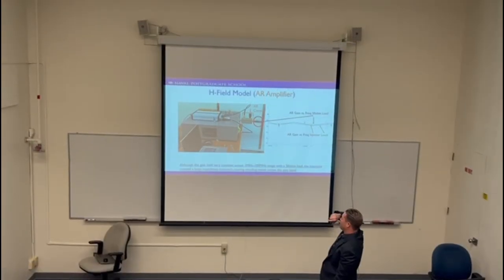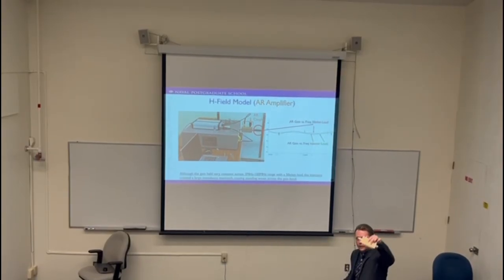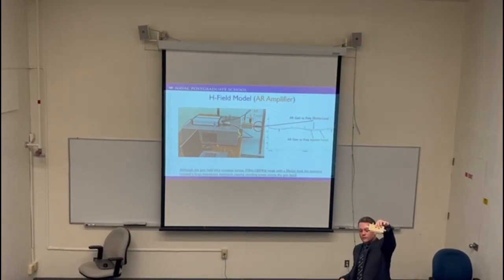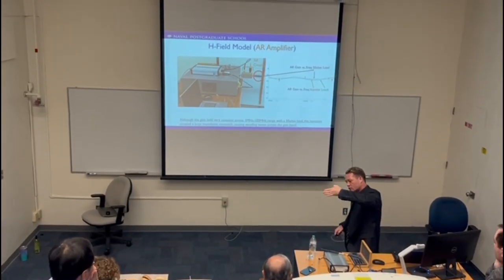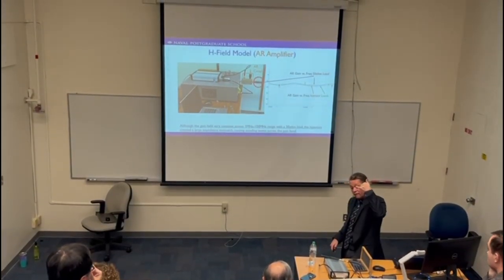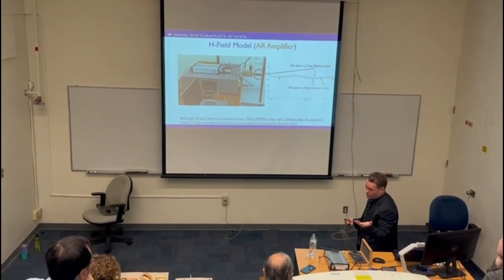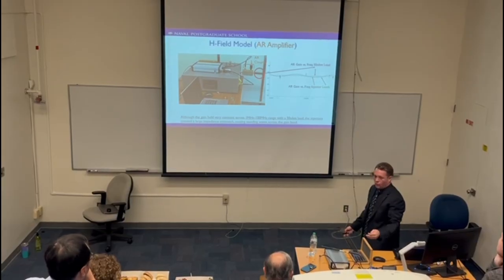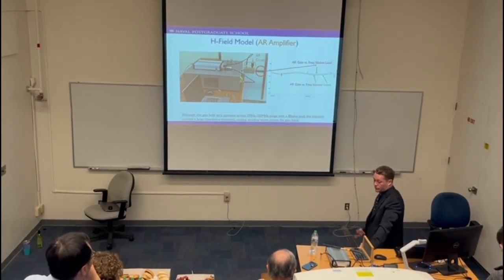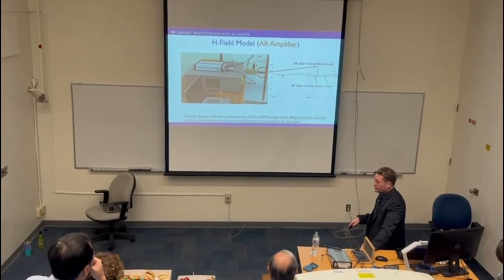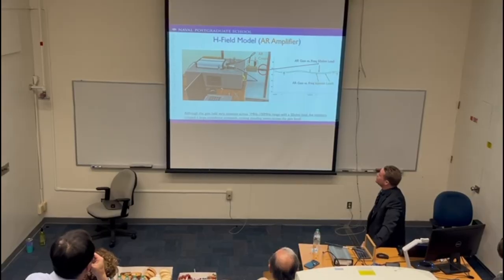To compensate for this super high power, I had to call in another friend and get what is called a coupler. This makes it very safe. I can look at what's on the forward line of the transmission line and pull that off at negative 40 dB down to feed it into my VNA without blowing out my VNA, because I couldn't take these measurements straight raw. I would blow this out completely. 20 dBm is the max this can take. So I had to cut it way down. I had to use a lot of attenuators and a lot of different things to protect it. I had to use 100 watt resistors.